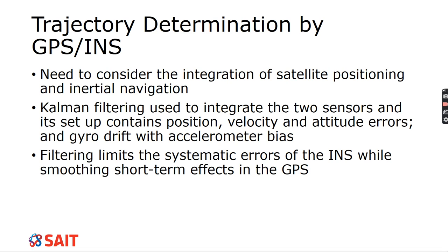So another thing that is considered is this trajectory by the GPS and INS. Because if you think about it, when the sensor sends down its data, it sends and then it receives. After it has sent down the laser information and it is returning back, we have a change in time. So we time the GPS and INS to collect the data by the time that it has been sent and received, and the airplane's continuing to move, so the GPS and INS have to predict where the airplane is going to be as it's receiving the data.